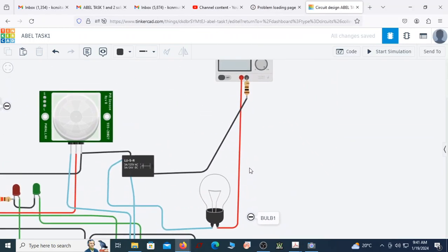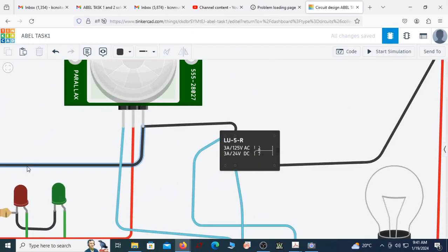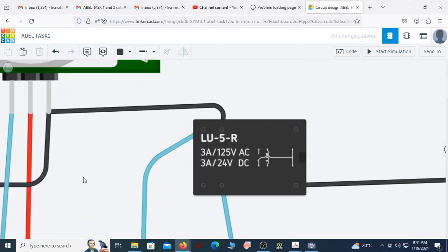So this is very simple. You may have to identify those NC, NO and coil. You can see these two are common terminals. This is coil and this is NO, this is NC. No need to remember if you have a look at this carefully. So this is naturally NC and this is one end of the coil. This is one common terminal, second common terminal, both are same. This is one end of the coil, this is NO. So let me run this.